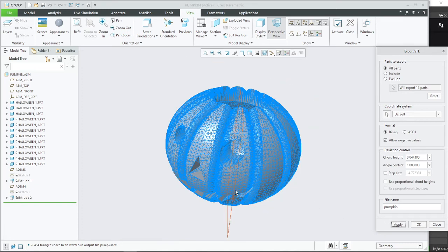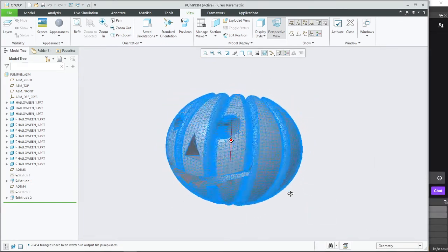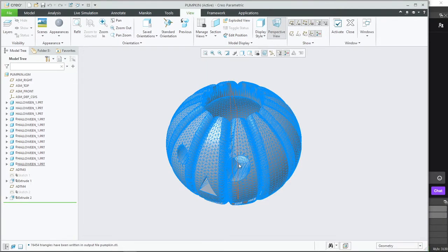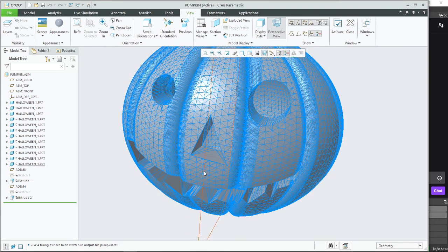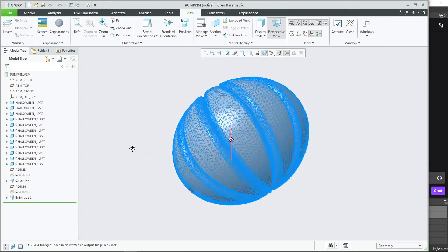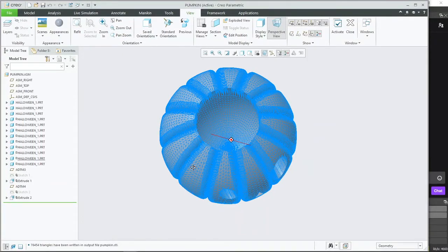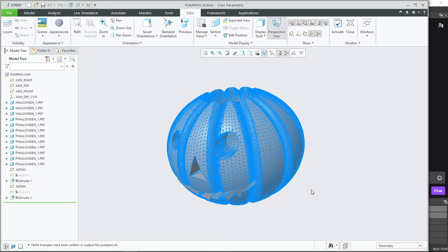Here are your polygons. Ta-da! Oof. Yeah, that's oof. That's a lot of polygons, right? Yes. You need this for 3D printing, because if I didn't do this, all the curves will no longer be curves because of tessellation. You need the exact opposite of this if you're making it for games or really even animation. Exactly, and that's one of the biggest issues with 3D printing.